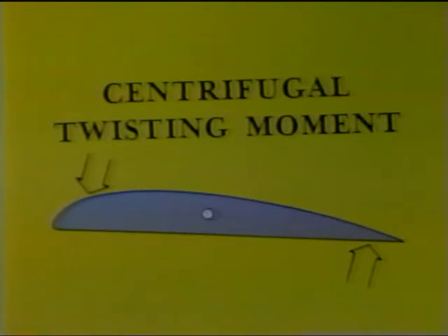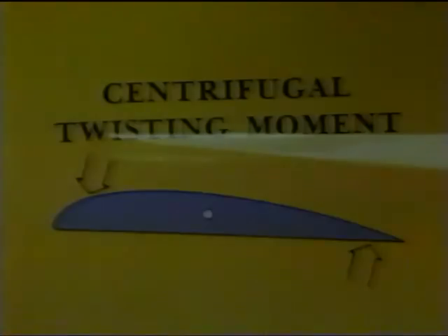Centrifugal twisting moment tends to decrease blade angle. This is caused by all parts of a rotating propeller trying to move in the same plane of rotation as the blade center line. This force is greater than aerodynamic twisting moment and is used in some designs to cause a decrease in blade angle. Propeller blades are also subject to a number of vibratory stresses. By this we mean that a propeller blade will start to vibrate when it is excited by some external alternating force. If the frequency of this vibrational force coincides exactly with the natural vibrational frequency of the blade, resonance occurs.